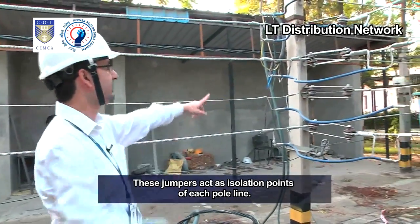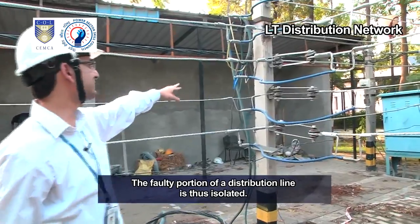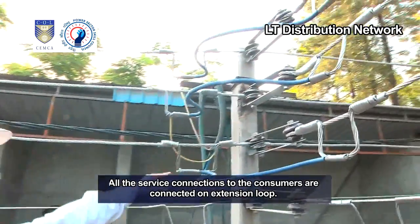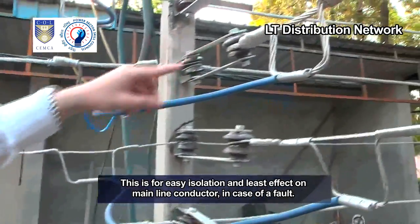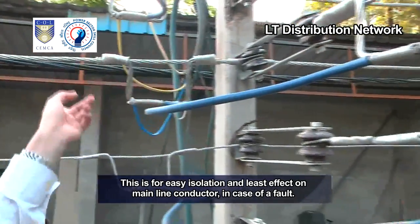These jumpers act as isolation points of each pole line. The faulty portion of a distribution line is thus isolated. All the service connections to the consumers are connected on extension loop. This is for easy isolation and least effect on mainline conductor in case of a fault.